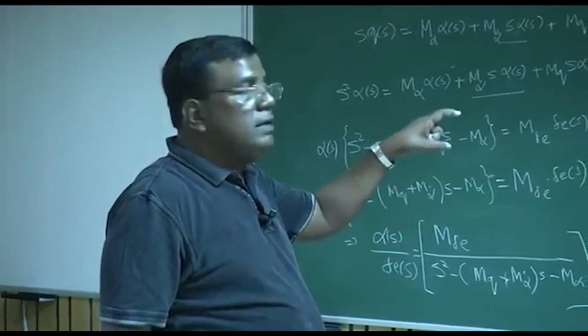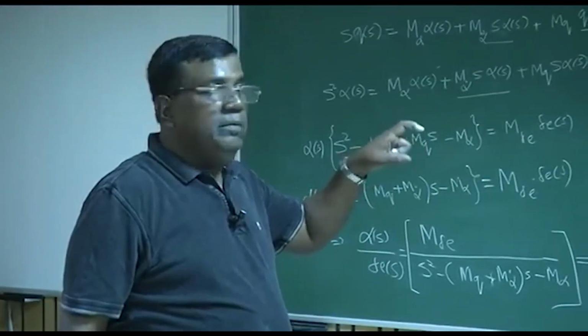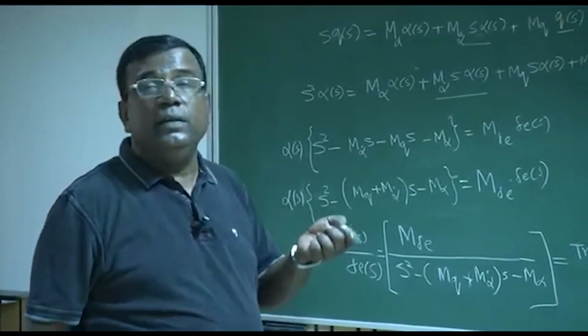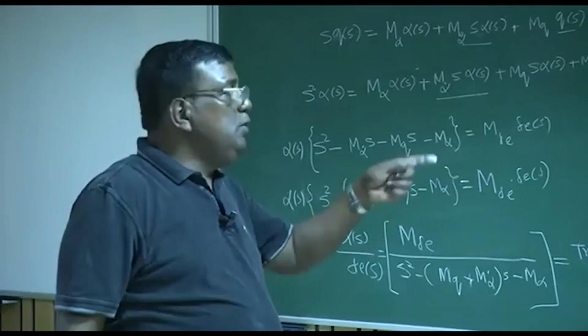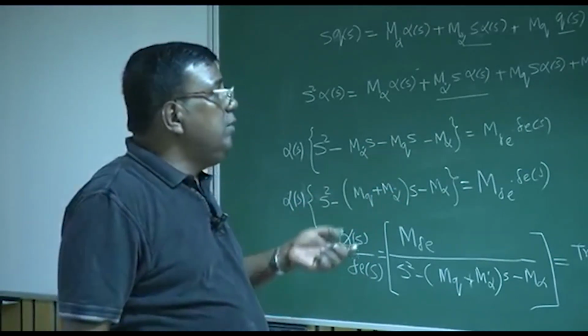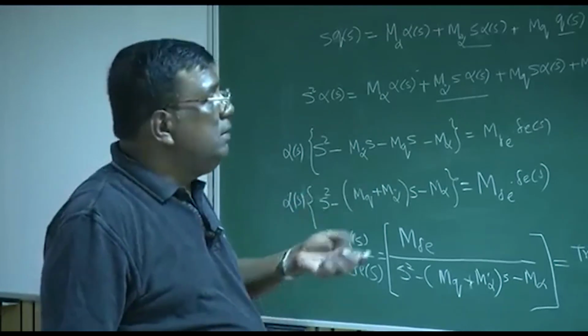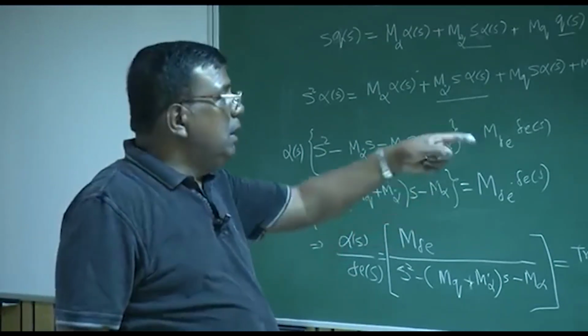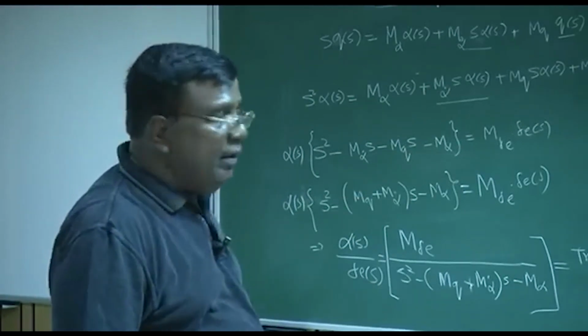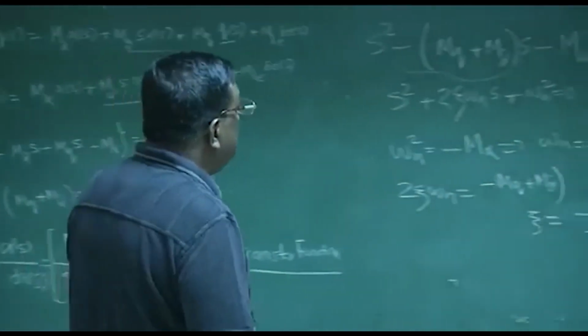So this sort of understanding makes you very comfortable, because you know the zeta you want maybe 0.6 or 0.5. So immediately you can see what is the MQ required, what is the M alpha required. If I want natural frequency of 13 hertz or 10 hertz or 2 hertz, I know what sort of configuration is required for me, and quickly I can find out those derivatives.